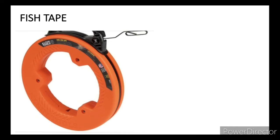The next tool we have here is fish tape, also called a pulling type duct threader, which can be classified into steel fish tape and fiberglass fish tape. It is widely used in pulling electrical wires through electrical conduits. The term fish comes from the fact that it's nearly impossible for us to push a wire through conduit, and then we must first fish the tape through the conduit.